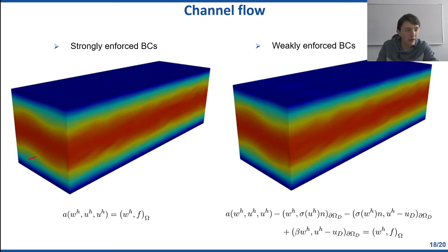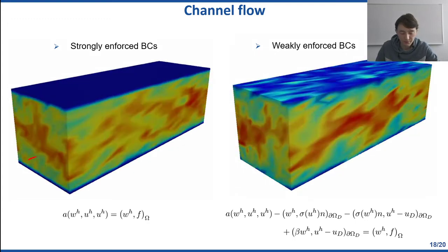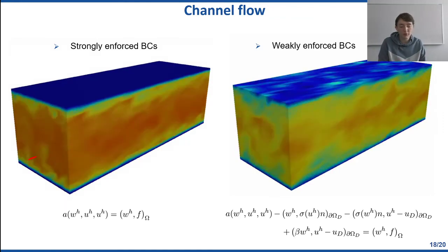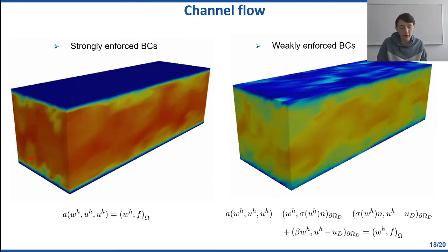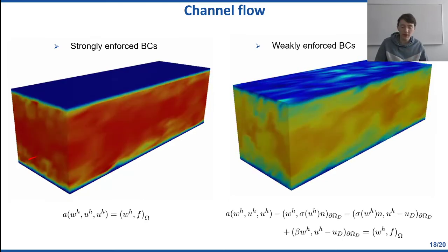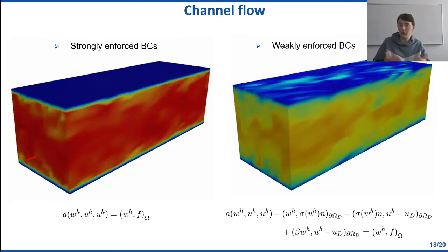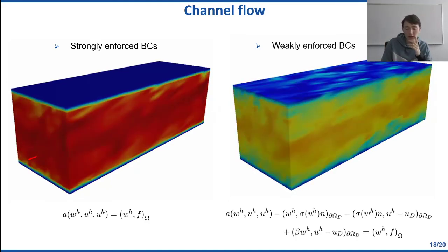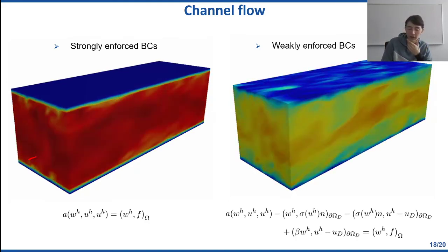So on the left here I have the same simulation that I ran a second ago. On the right I have one where I'm using a discontinuous Galerkin type method, where I'm allowing flexibility on those boundaries. So that's what you're seeing right now. On the top and also on the bottom of the picture on the right, you see that the constraint that the velocity is supposed to be 0 there is a little bit relaxed. We're allowing a little bit of slip. And only in a weak sense, and we'll talk about what that means, are these constraints satisfied.